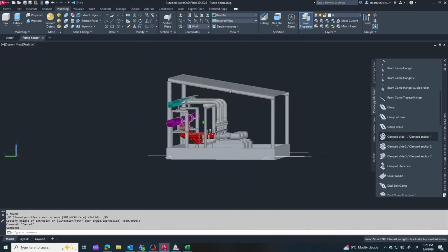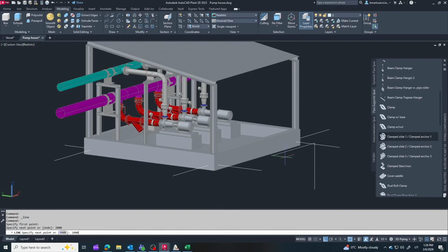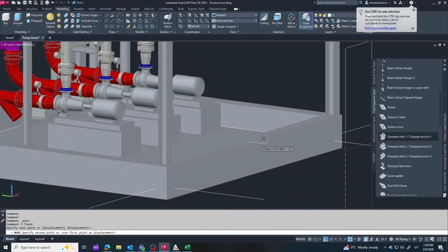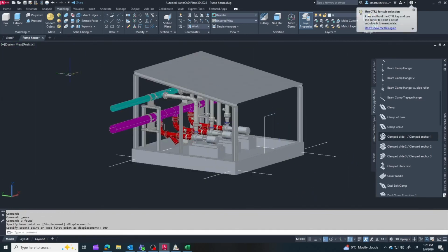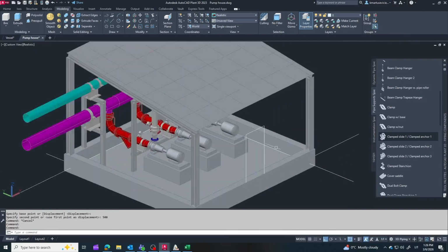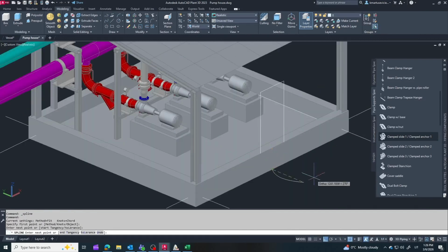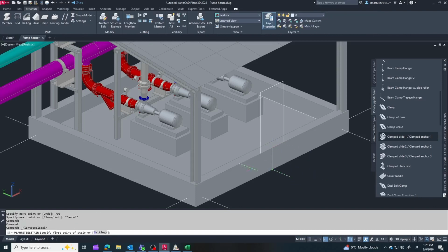Now I add a door in the middle of the front wall. I use a standard door size, approximately 1 meter wide and 2 meters high. The edges of the pit are raised about 700 millimeters, so we will need stairs to access it.